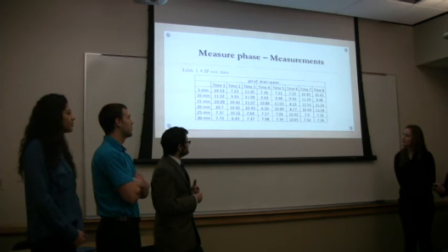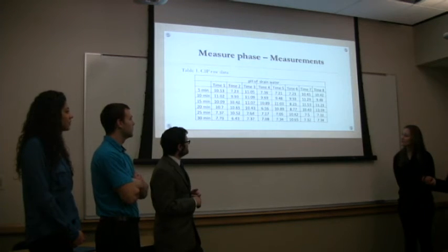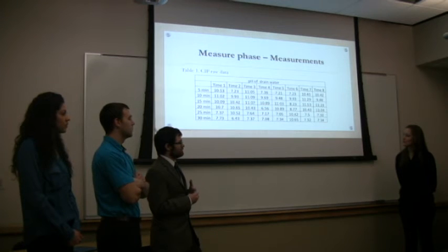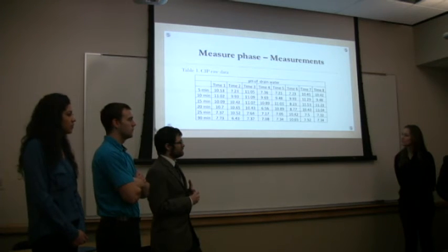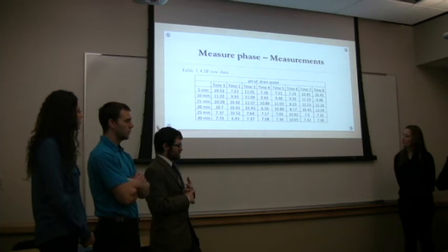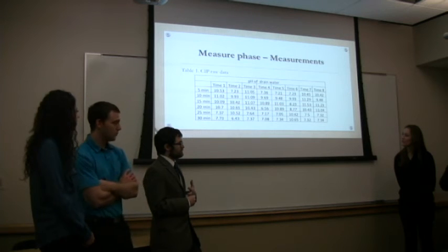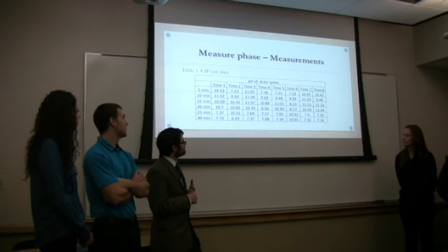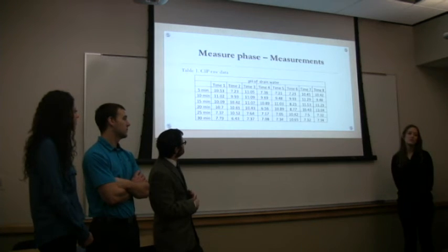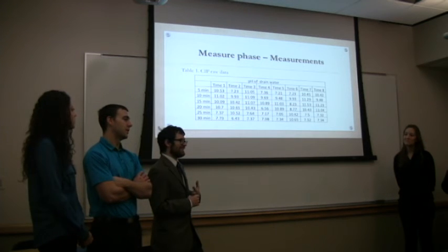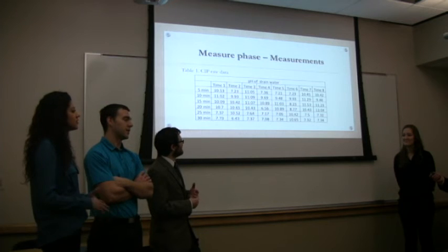Well, we could theorize that it's just random chance, or there is a possibility that at the moment we took the measurement, as it was getting rinsed, some leftover bits of the raw alkaline soap that wasn't necessarily homogenized with the citric acid might have hit the drains at this particular point in time, which jumped the pH up suddenly. Or we could have put the data in the table upside down. I think that's probably what happened.